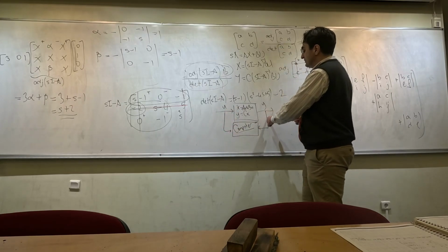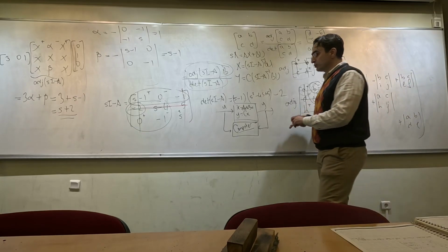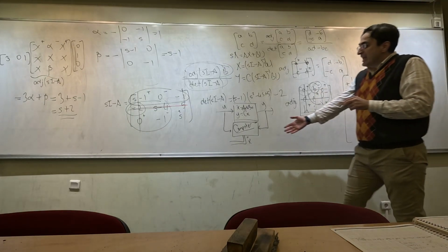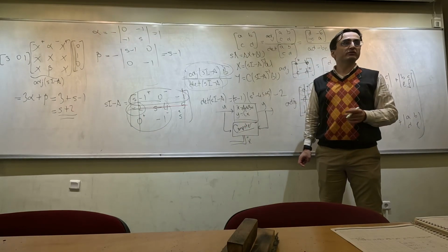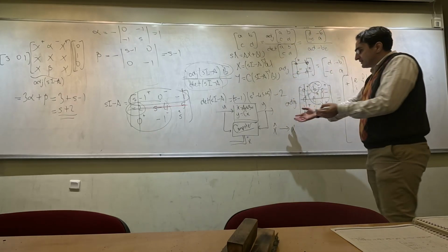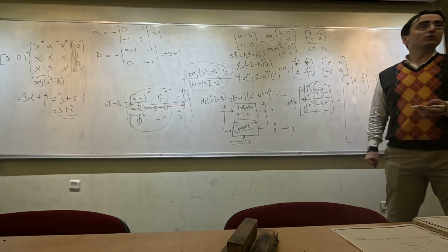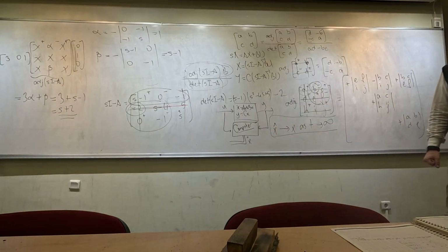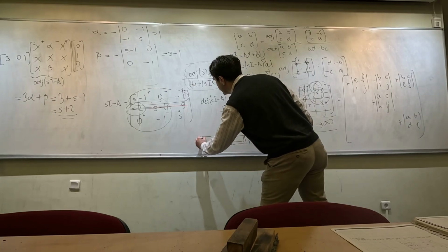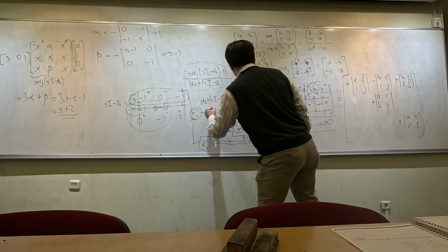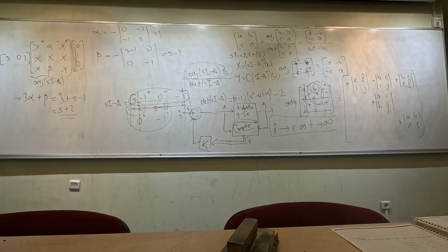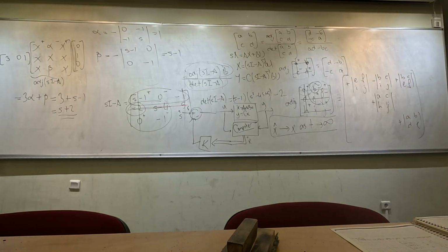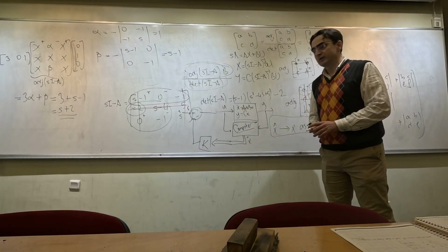So by taking this u and this y, we can design a differential equation which is going to give to us an estimate of the state. This is called x hat. Okay? So my aim here is that this x hat should converge to this actual state x. So we want here x hat to, even if at the beginning they are not the same, converge to x at the end as t goes to infinity. That is what we want from an observer. And after getting that state estimate, instead of feeding the actual state, we can try to feed its estimate back. Okay? Then if this estimate converges to the actual state sufficiently fast, then the control system would behave really nicely without even measuring the actual state.